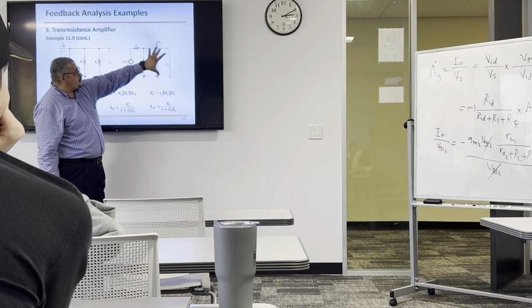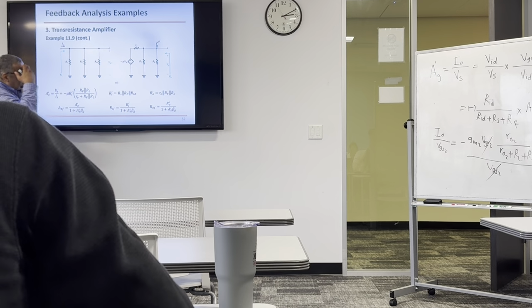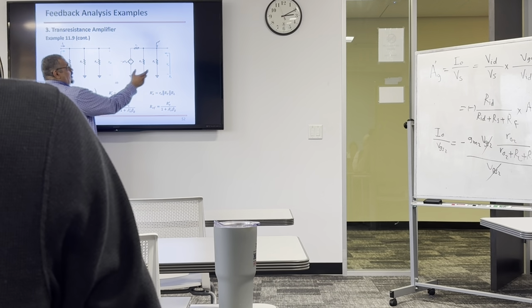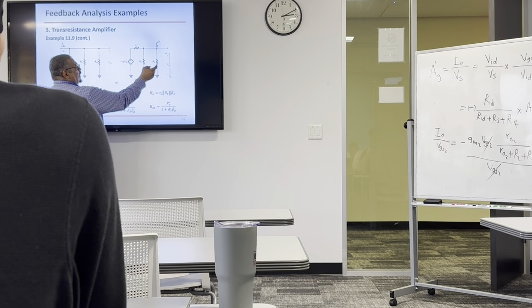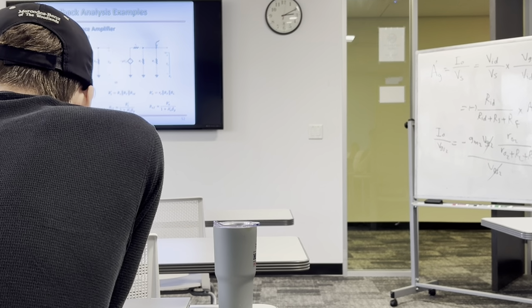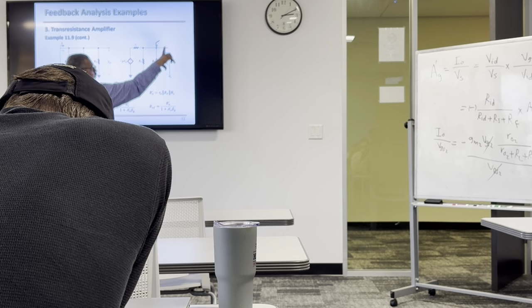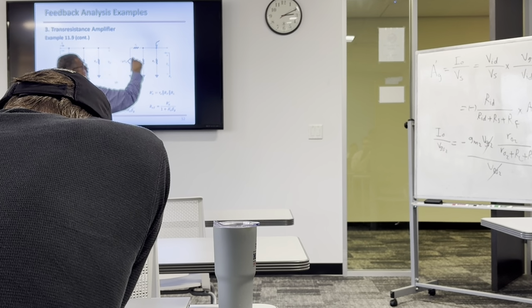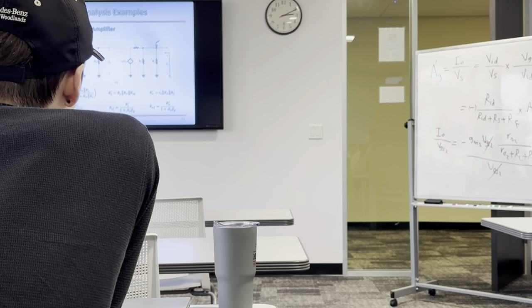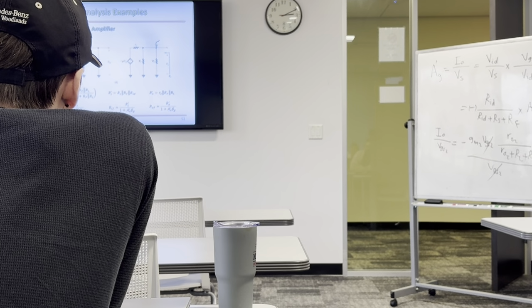How are we going to find this voltage? What's the relationship between this and this? R naught plus RL parallel with R. Exactly, RF and RL in parallel. And these two are in parallel, and you do voltage divider with RO. Okay, so these two are in parallel first, because the V out is across these two. And then you take voltage divider. And you apply this, you're going to give you this. Okay?